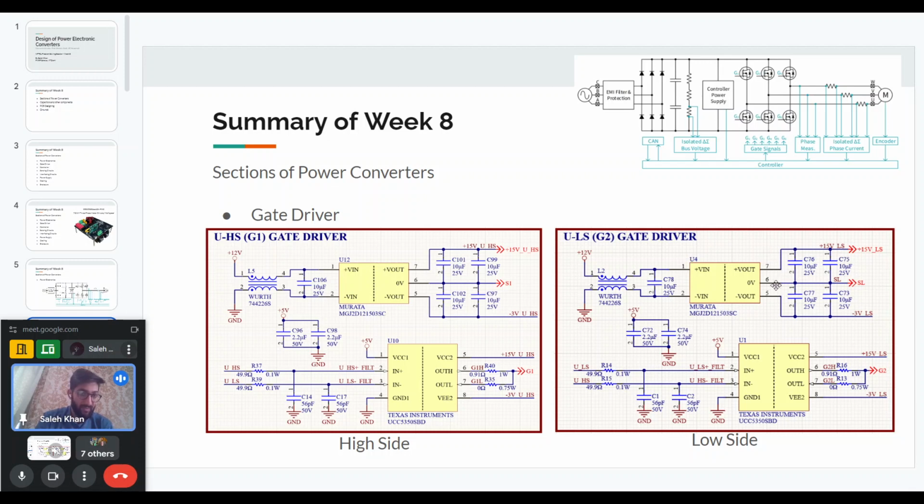They have used one of these, and it provides the voltage supply to all 3 gate drivers of the low side switches. So this is one low side gate driver, which has the supply and the gate driver IC. The other two will only have the gate driver IC. They will not have a separate supply because this same voltage is used for those two as well.